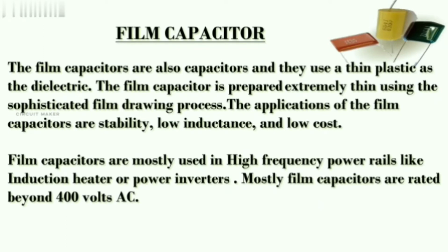If you take a look at cheap power supplies, you can see such capacitors are put in series with the mains input for dropping 230 volts AC to the desired output voltages. Such power supplies are mostly used in electric mosquito killer bats for charging the battery.